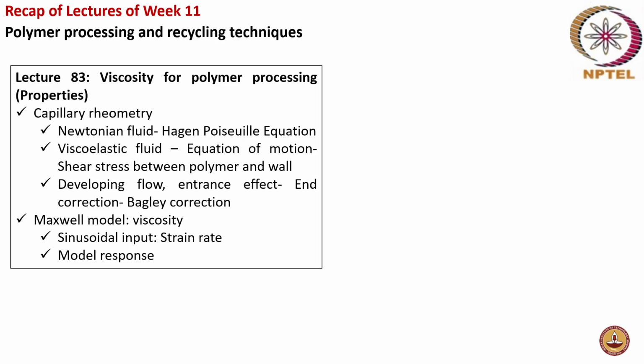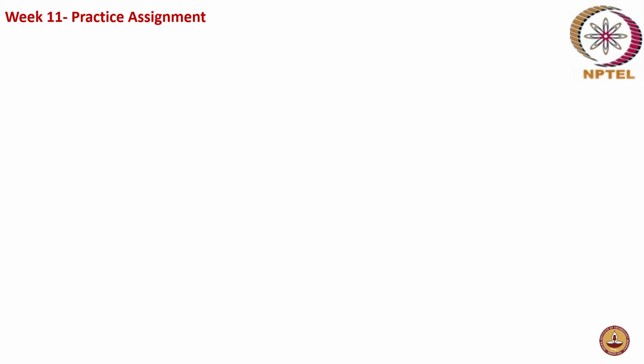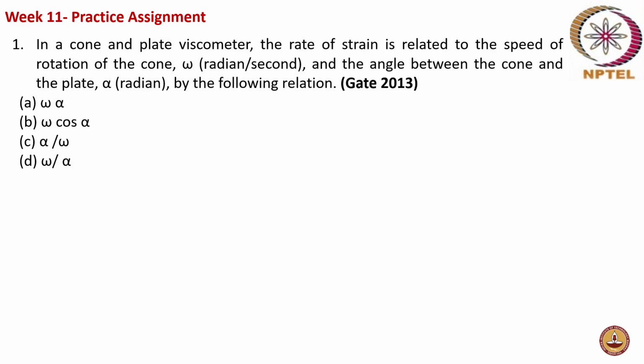When you have the entrance effect where the flow is not fully developed, you will have to apply end corrections. For example, Bagley correction can be applied. And then there was a discussion on the Maxwell model, where an oscillatory input of strain rate is given for estimation of the dynamic viscosity and the model response. So these were all discussed in this lecture. So that's it with the brief recap of the lectures of week 11. Now let's get on to the practice assignment session.